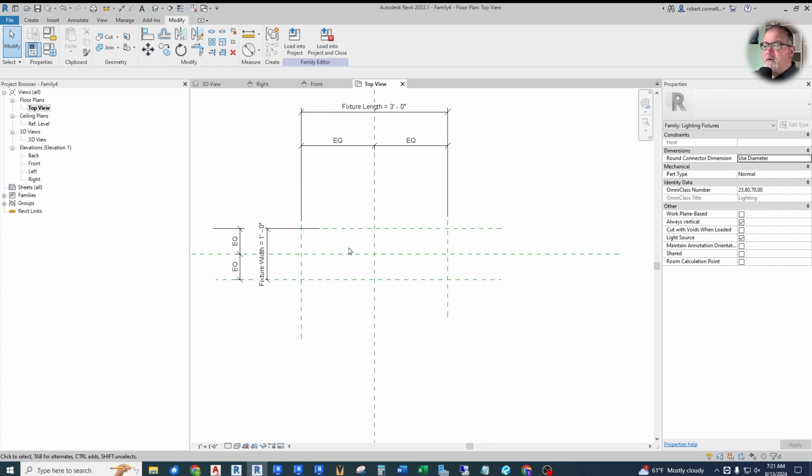If you're just using Revit right now in place of CAD, you don't have to have 3D objects. I personally suggest that you get there because the 3D aspects of Revit are very powerful, and you'll find that many clients request that 3D level of coordination. But if you're just starting out or you just need basic 2D drawings, you're fine. You don't have to do this, and you can skip ahead to the annotative symbol part. Anyway, we're going to do a full 3D model, even if it's basic, as well as a 2-dimensional symbol.